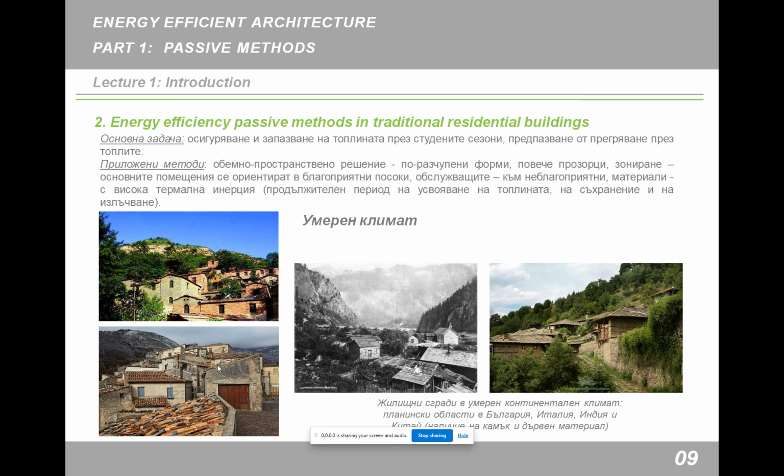The applied passive methods are a little bit more diverse forms, more windows, still not too big, zoning, orientating the main rooms with the main functions towards better orientation, and the serving rooms towards not so good orientation, using materials with high thermal inertia.